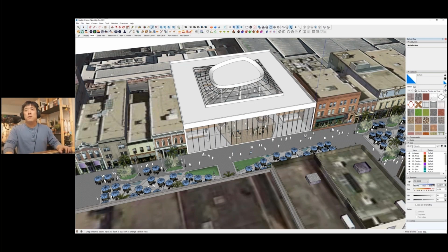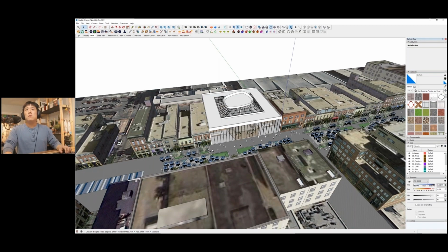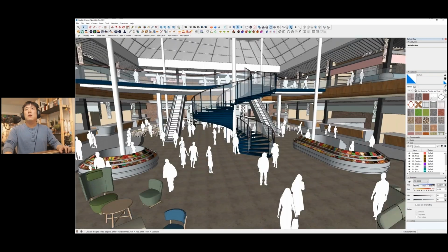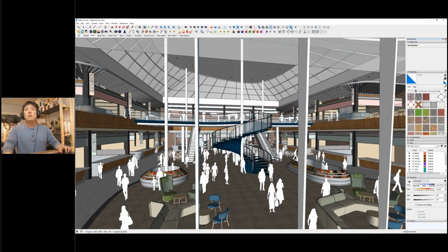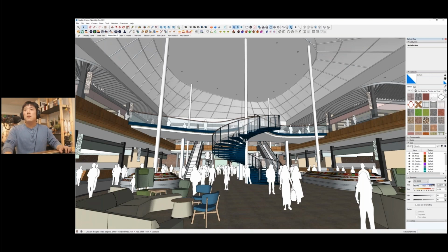By the way, if you have the default view on SketchUp, you can hit Z, or Zed for those of you who are across the pond. Then you'll see the field of view shown on the bottom right-hand corner, 35 degrees. At this point, you can type 60 DEG and hit enter, and that will widen the view for you. Often this is much better for navigation and showing clients the context of the things you are looking at, and it's quite helpful for your renderings too. So that's what I pretty much have done on this interior view here.